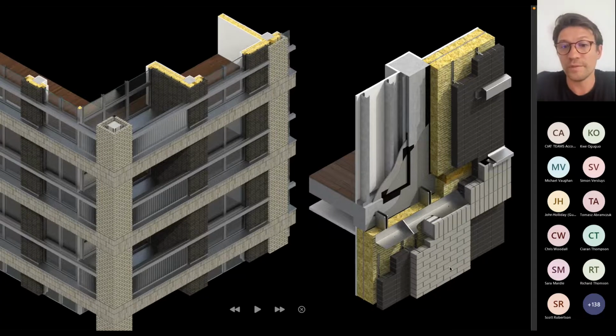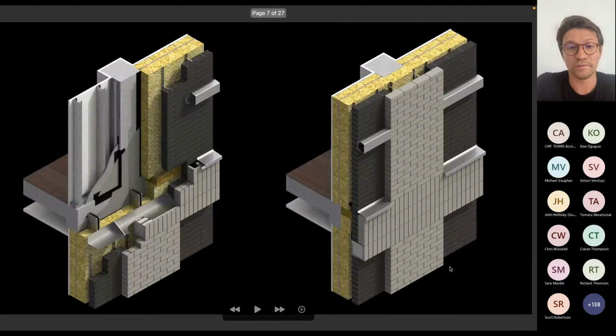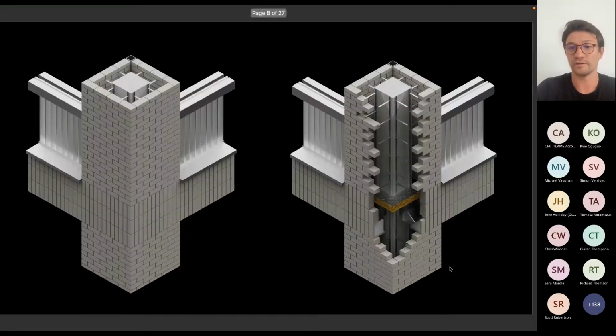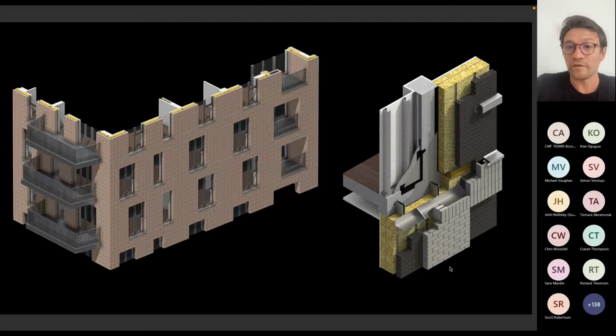So this assembly becomes somewhat expensive to achieve that outlook. These three details show what support that brick would require. And for these types of facade, where the windows are not stacked and the brick bond is not stretcher bond, it's really worth considering, for tall buildings, a brick slip facade instead of masonry.